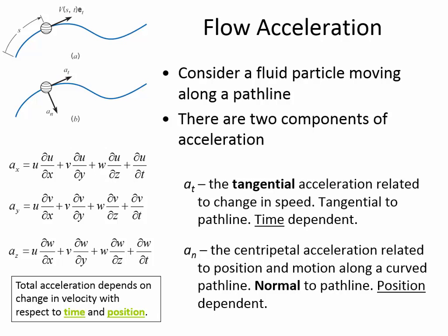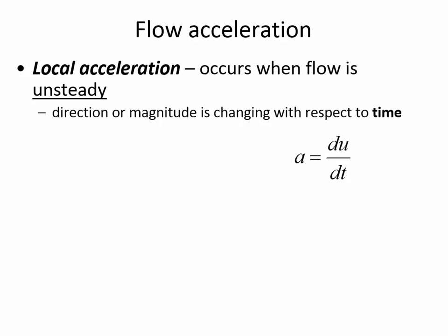When conditions were static, we had it pretty easy because all we had to do was apply the hydrostatic equation, which is simply that as you go deeper down into the fluid, the pressure is increasing at the rate of gamma. But when the fluid is accelerating, the pressure changes even horizontally. And so we have to be very careful in the way that we consider the effect of acceleration on pressure.